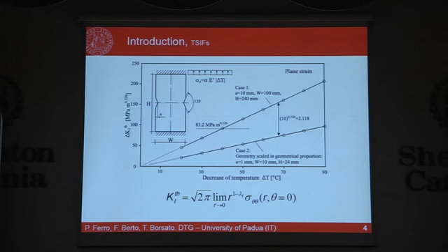And what is important is that the intensity of such stress distributions is quantified by the notch stress intensity factors, which is a parameter already used in literature for the assessment of the static, dynamic and fatigue strength of notched components.